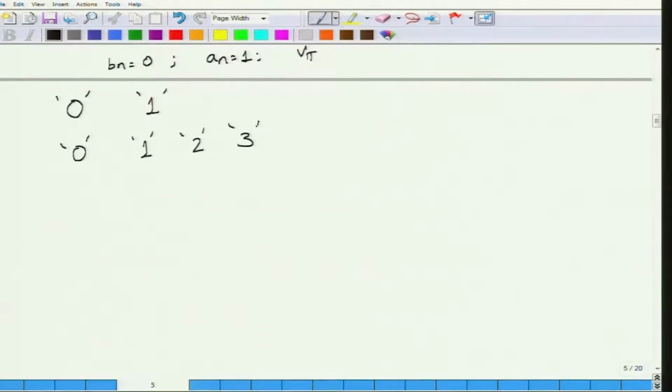There are 4 symbols now. My alphabet includes 4 letters, right. The size of my alphabet is 4 essentially, and I want to change the amplitudes that would correspond to 4 different levels. Earlier I was changing the amplitude corresponding to 2 different levels. Now I would like to change the amplitudes corresponding to 4 different levels.